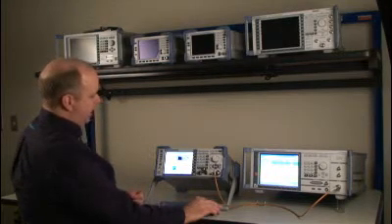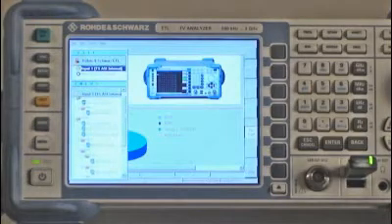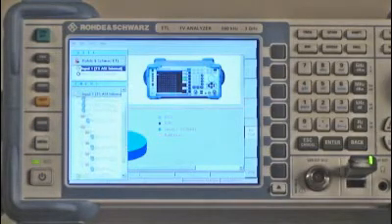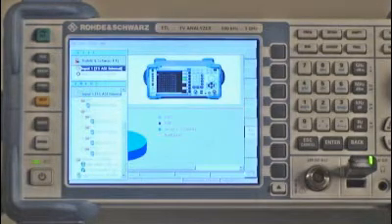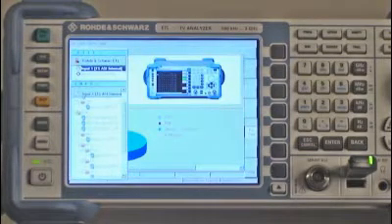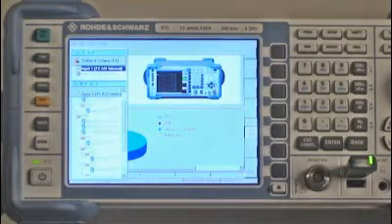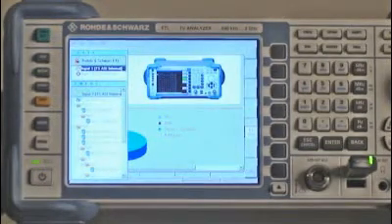I can also come in and actually look at the transport tree. This will show me all of the PIDs within the transport stream, including the video PID and also the audio PIDs. Null packets, I can go in and look at my event information table, and I can go in and look at PSIP specific information, predominantly the master guide table, which lists all the other tables within the PSIP area.